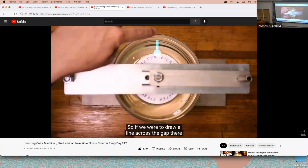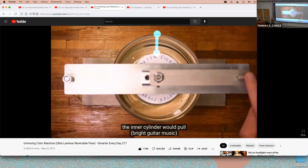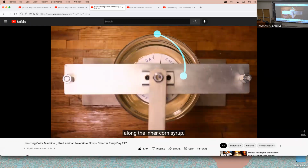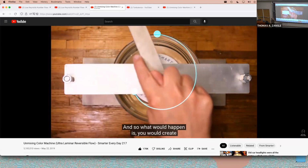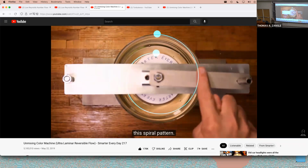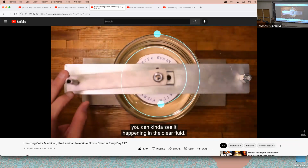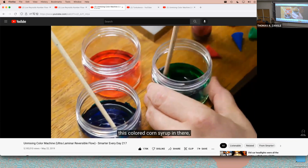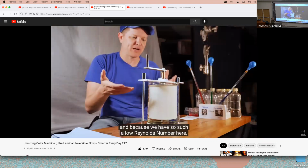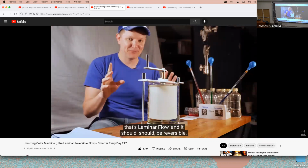So if we were to draw a line across the gap there, and we were to rotate it, the inner cylinder would pull along the inner corn syrup, and the outer corn syrup would stay there. And so what would happen is you would create this spiral pattern. In fact, if you look down through there, you can kind of see it happening in the clear fluid. So what we're going to do is put this colored corn syrup in there, and because we have such a low Reynolds number here, that's laminar flow, and it should be reversible.